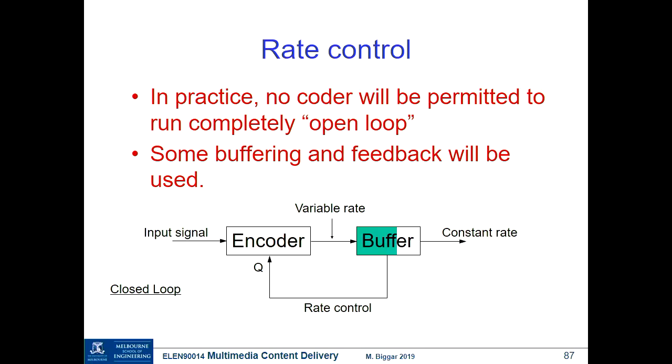In Australia, it's a 7 megahertz chunk of spectrum, and that turns into about 20 megabits per second, and they can do whatever they want with that, but it's fixed at 20 megabits per second. They would want to be reading this data out at a fixed rate. It's a little more complicated than that because they combine several TV programs together in the one bit rate, but it's a good enough model for our heads.